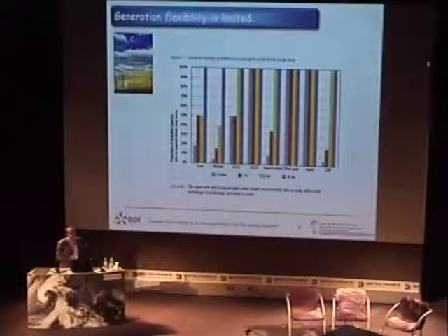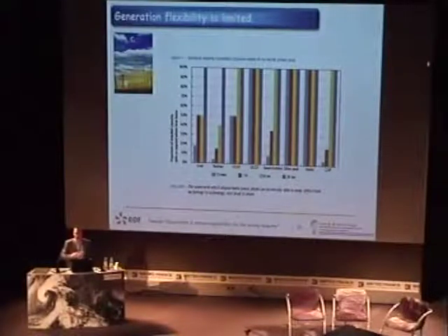And on this picture, you can see clearly that some production means, especially hydro, for instance, can answer quick variations in the load, so quick variation in production, in all the time scales. But you have also means of production, in particular nuclear and coal, which cannot answer very rapidly. That's to say that you need to plan the increases or decreases in the production for those production means.